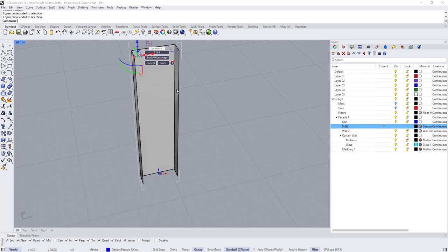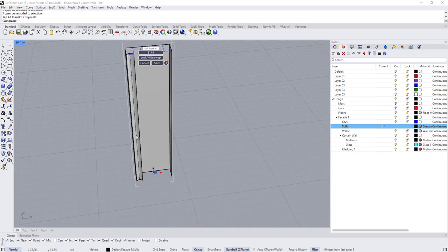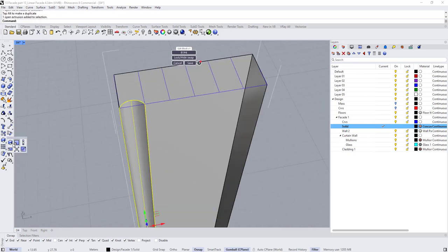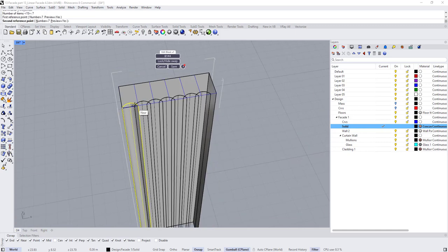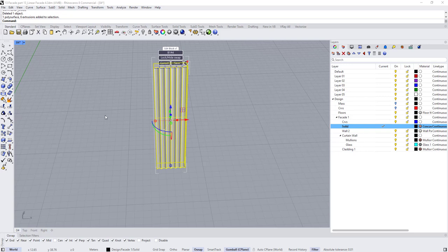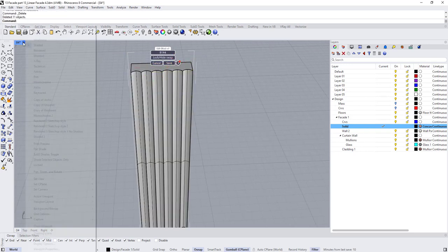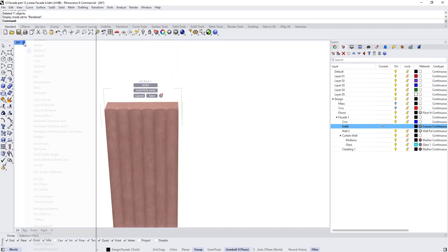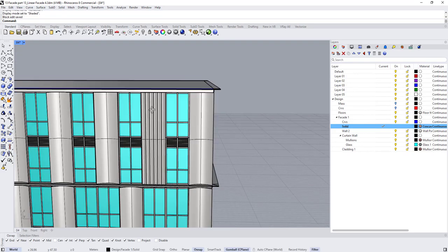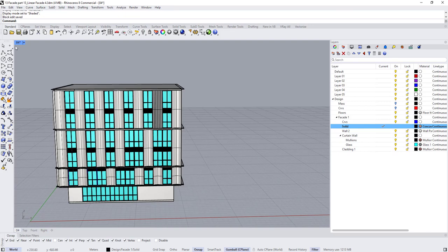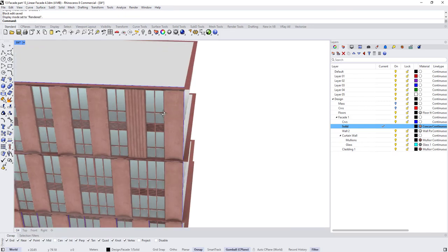And select the solid layer, extrude here by a value of 7.7. Select it and create a copy. Choose a linear array. The number is going to be 7. From here to here, delete this one. Select all of this, press Ctrl J, type cab, close it, select this curve, delete it, switch to render view. And this looks cool. And okay. So switch to the render view maybe.